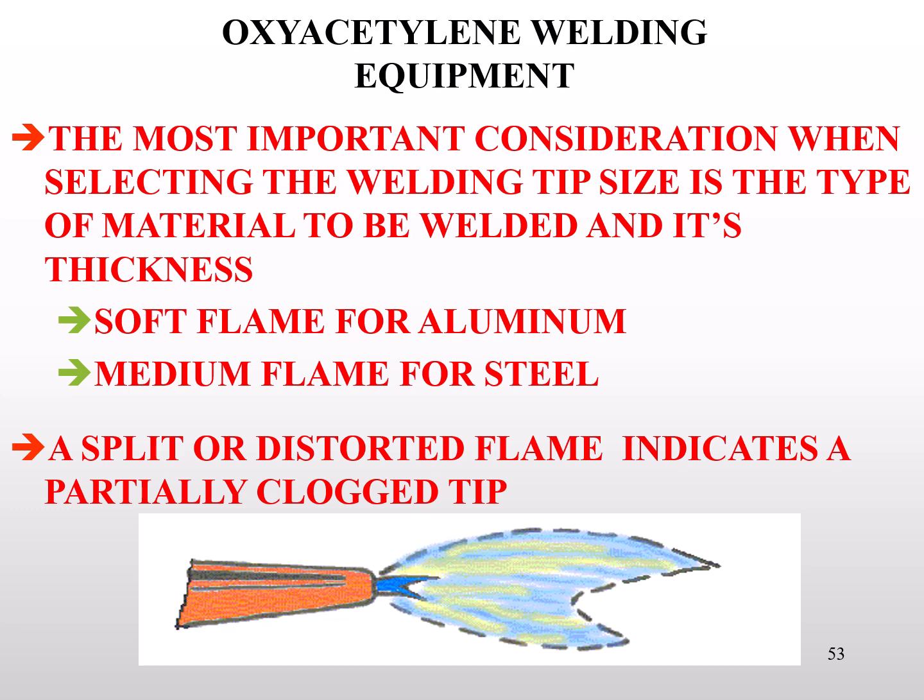This is a key thing in creating flames because each tip size works within a range. If we want the low range, often we're going to run lower pressures. If we want more heat produced, we'll have to flow higher pressures, burn more gas to produce more heat. However, each tip size has a limit. If I try to flow too much gas out of too small of a tip, it'll cause the flame to be harsh. And a lot of materials won't tolerate a harsh flame.